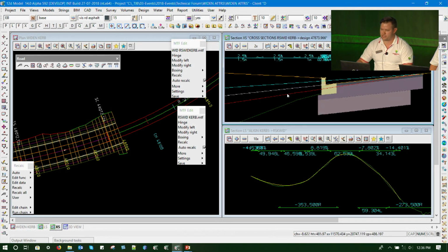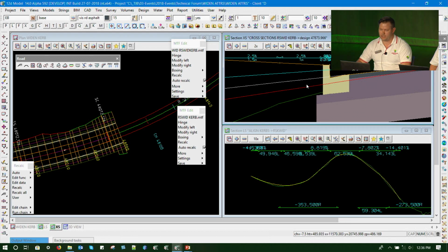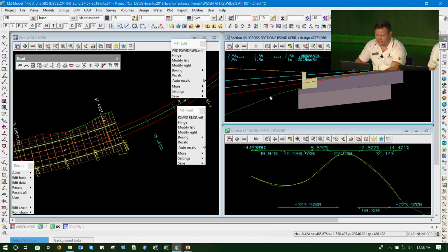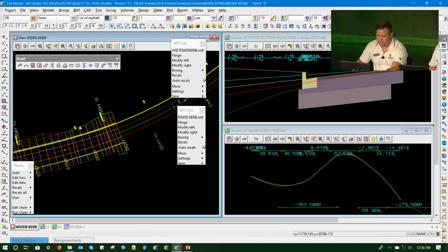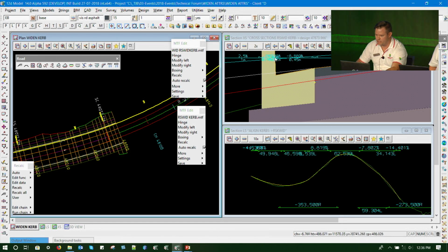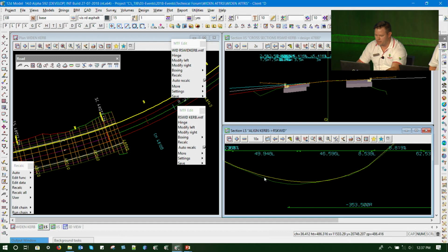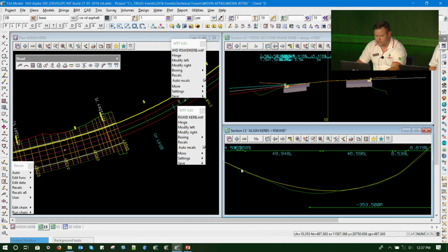And you'll see in my cross-section view, with the TINs already turned on, it's created a 2% crossfall envelope, positive and negative each side of the existing crossfall. So I've already prepared an alignment earlier in the plan view. There it is horizontally. In the cross-section view, I'll turn it on. You can see it's down lower, a little bit outside the envelope on that one. All good. In the long section view, I've already graded the alignment vertically just to save some time.